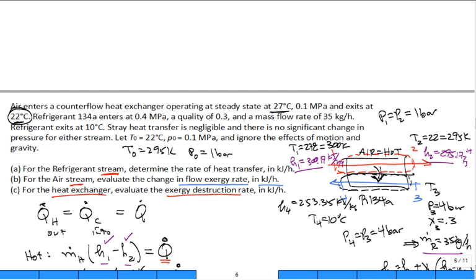And what about our temperature of the refrigerant coming in? That temperature at 3 is the saturation temperature of the refrigerant coming in. It's like 8.9 degrees C. Compare 8.9 degrees C to 22 degrees C. It's cold, right? Likewise, it goes out at 10. It's cold compared to 22. So at this point, to make more sense of it from an exergetic perspective, I would set that dead state temperature to like negative 40 degrees C and redo it.